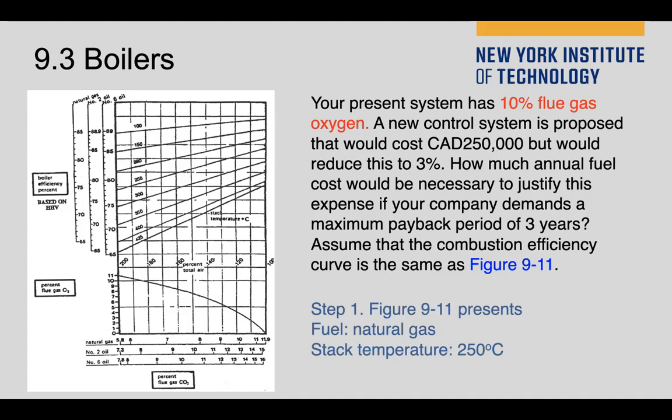Can you repeat that, like the relationship of the percentage with the efficiency? Okay. So for the first term, the fuel gas oxygen, you need to know what that is. The fuel gas oxygen is the percentage of oxygen that remains after the combustion. If there is a higher percentage of oxygen, that means the combustion had extra high oxygen.